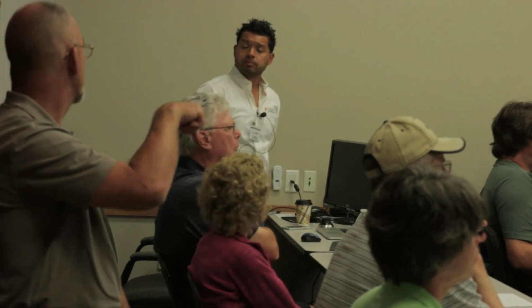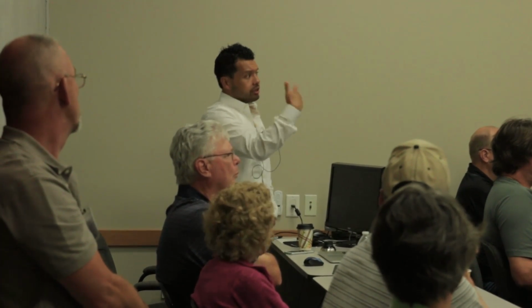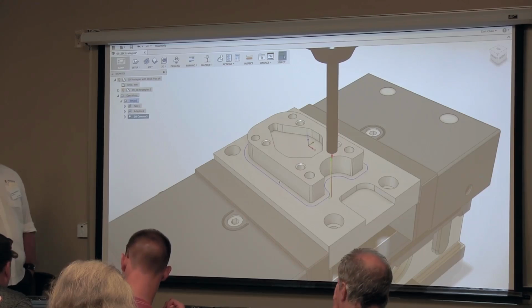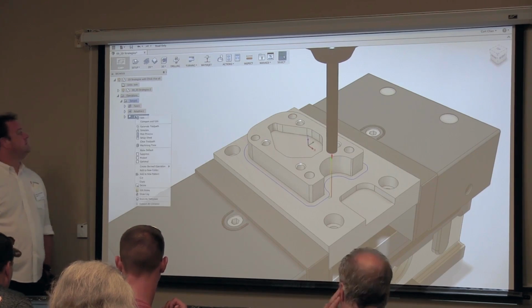Yes, sir. Is it always climb milling? Is that a default? Helix. Yep, by default, it's helix, we call it. Or technically, I don't need helix, right? Because if I have to machine 100 of these parts, or I have this on a tombstone, if that extra helix takes me an extra minute times how many on your tombstone, 30 or whatever, that's 30 extra minutes of it helixing down. So what we can do, just for demonstration purposes, I'll show you